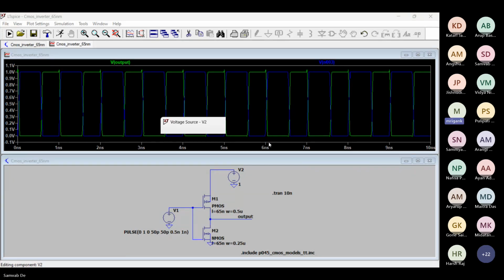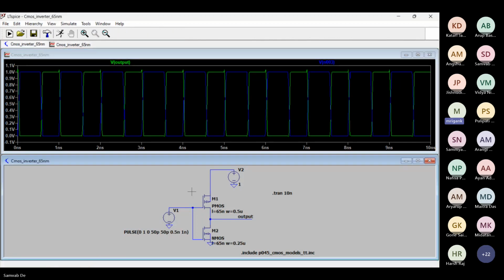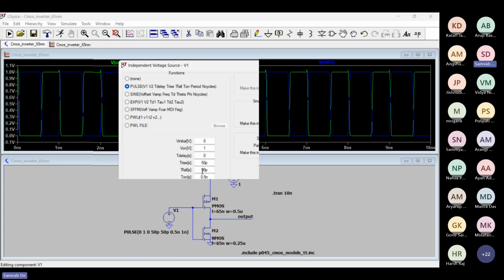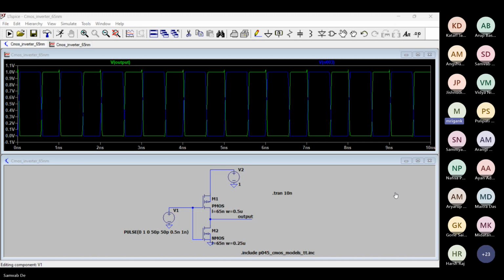Yes. So where do you enter the parameter? Show how you are entering the parameter, for the VDD and the pulse source that you have put. These are the parameters. Here you can see different options for the source: pulse, sinusoid, piecewise linear, which is used when you have a data table from which you can generate the source. But if you choose the pulse source, as he has done in this case, you can go to the parameter window. Why did you close it? Just open that window.